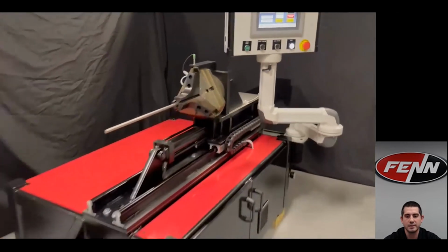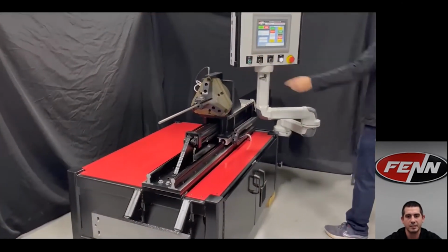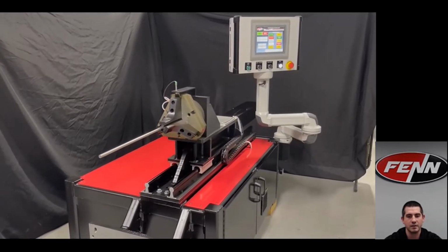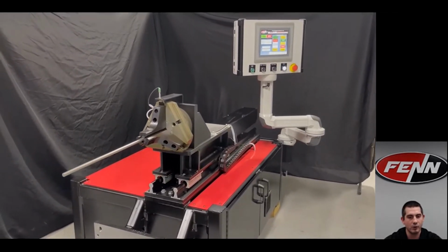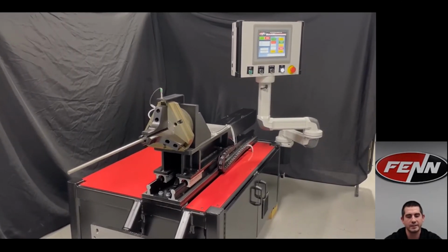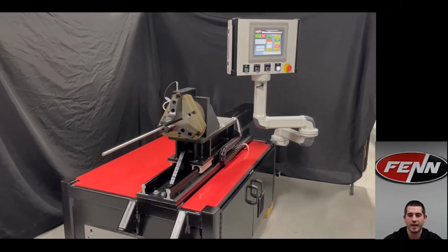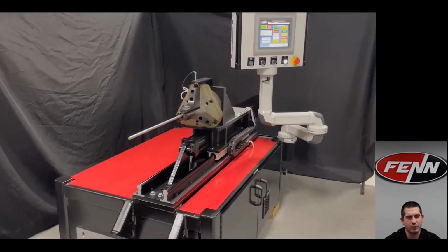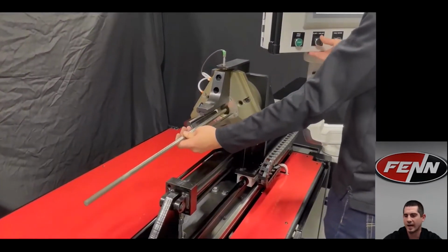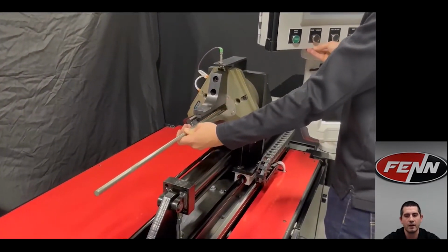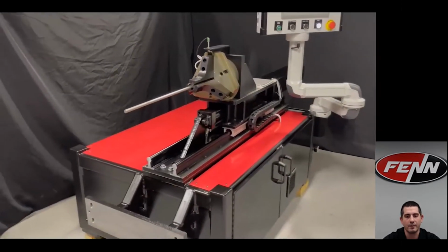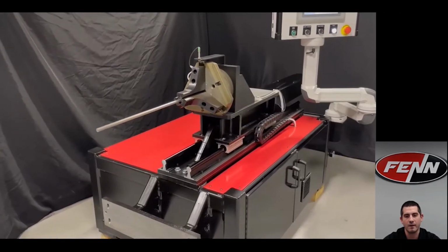As you can see, this feeder has a programmable HMI screen, and the benefit of that is your team has the ability to create recipes. You can save your variables, download them, and then run parts in the future that you have already run before. And it really takes the operator out of the equation. You don't have to train an operator to remember any of these parameters or variables. And if you have turnover or anything, operators retire in the future, you have the ability to have someone step up, download this program and start running your parts as you were before.